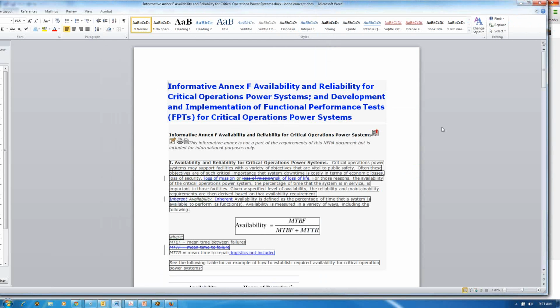So if you have a district energy system, it could be gas turbines or whatever producing power, and you can arrange your distribution system so that critical loads can draw their power from either the utility or the district energy system, that can have much more impact on improving reliability than just grabbing another